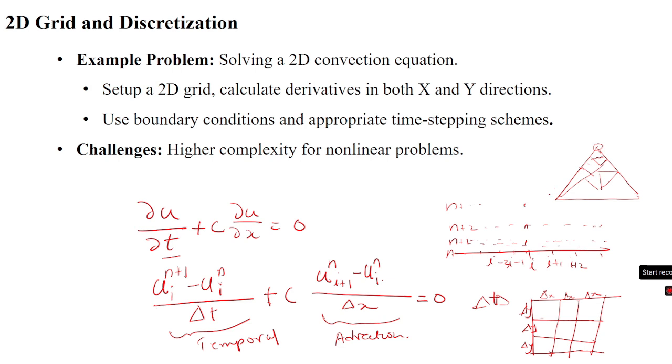Now one solution is to use an unstructured or non-structured grid that adapts to the irregular geometry. For example, we can create a triangular grid that fits the cavity shape, or place finer grid points near the wall where the flow gradients are higher, allowing us to capture the velocity and boundary layer properties more accurately.